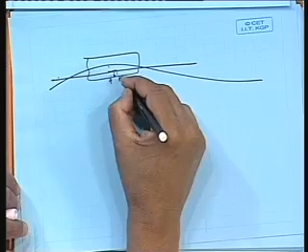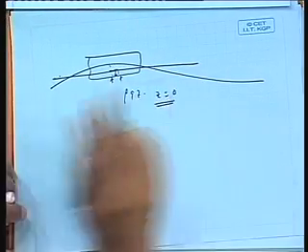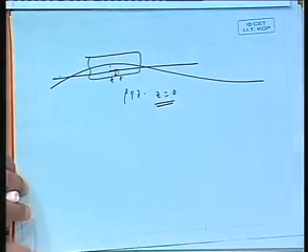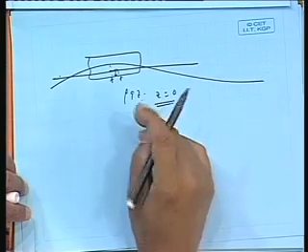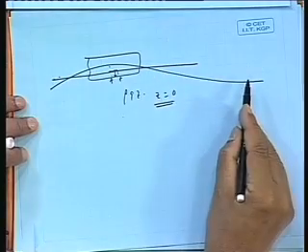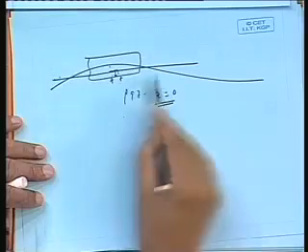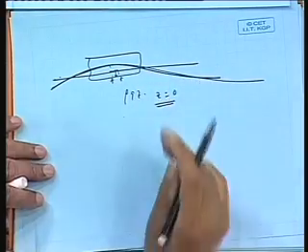So in this case, if you have to use rho g z for pressure and measure z from the z equal to 0 line, you have to necessarily add the dynamic pressure. If you do not add dynamic pressure, you are doing it completely wrong. So whenever we are looking at a wave, whether it is a small or big wave, you either have to take the total pressure, or if you do not want to take dynamic pressure, assume that water is not moving and that this is my free water line, the calm line, and from there you measure. This will come out positive. Yes, it will give the correct value.